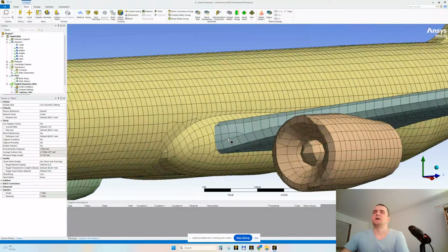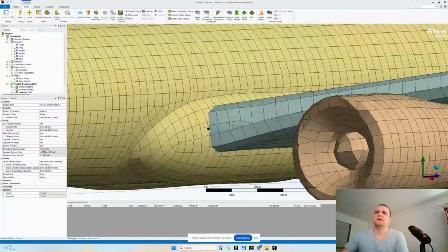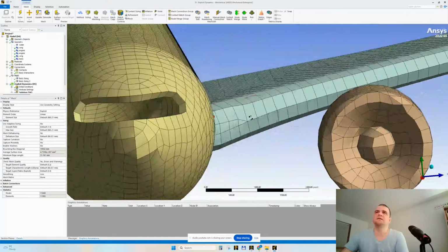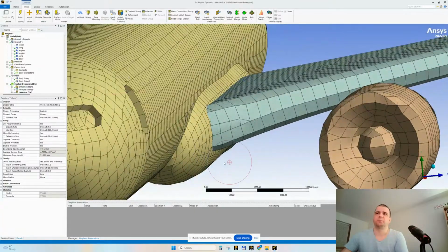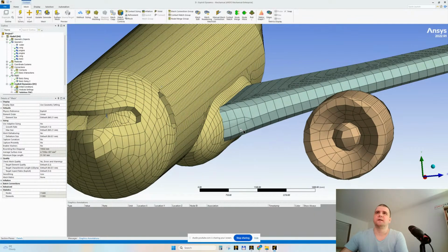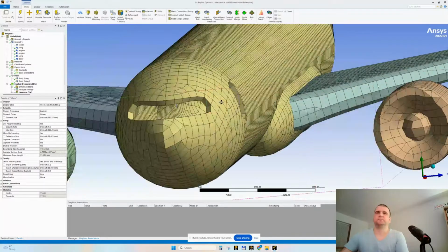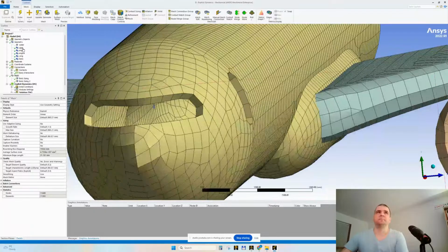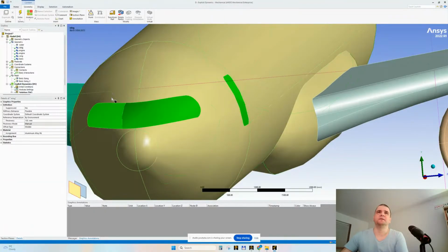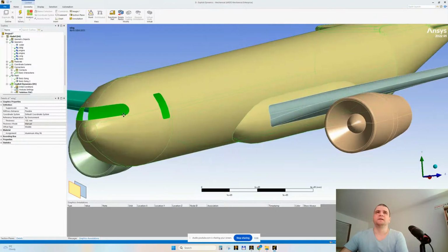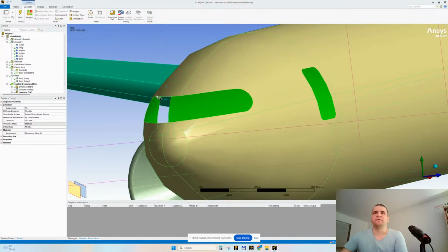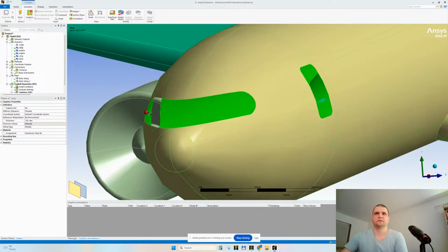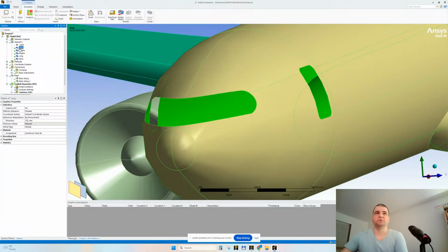You can maybe ask me, hey, why it's like a collision? It's only like an impression, let's say, because the middle of this is the middle of the shell. So from the middle, we have 50 millimeter offset on both sides in order to achieve the 150 thickness.